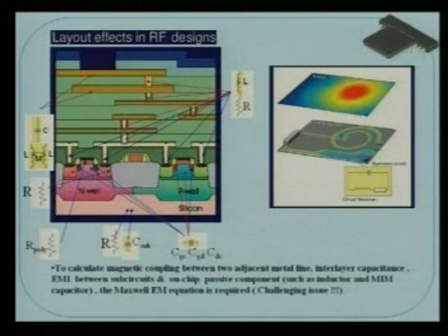At high frequency there will be mutual coupling, so you can effectively model two running wires separated by the oxide layer as a capacitor and a mutual coupling. For example, look at those vias. Vias are what? From metal 1 to metal 2, level 1 to level 2, they are connecting.